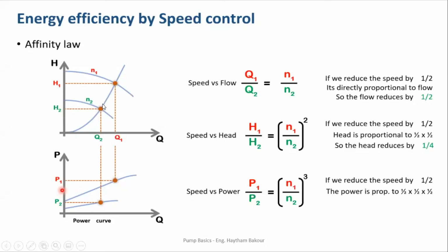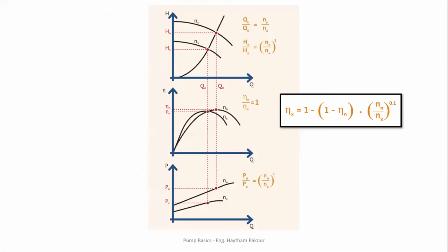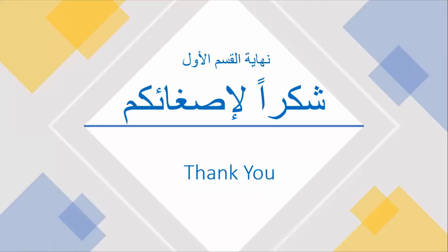Maybe if it drops below some values, the pump would work without sending any water, which would result in increasing heat and malfunction later. From this study, we can see the efficiency of the pump would change based on the rotational speed. Many things at the end.